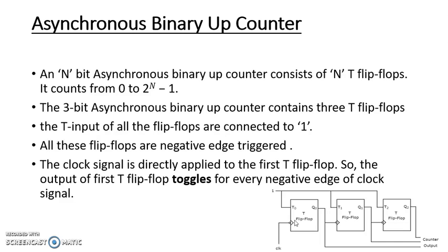In the 3-bit asynchronous binary counter, we have three T flip-flops, and all the T flip-flop inputs are connected to logic 1. All the flip-flops are negative edge triggered. One more very important point is that all the flip-flops' clock inputs are not commonly connected to a common clock input signal.